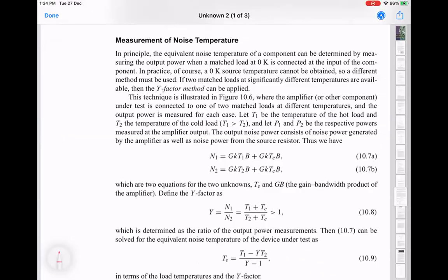So this is a model for an amplifier just from the input and output. It looks like a resistor for anything that is connected to input, and that resistance should be 50 ohms. And it looks like a voltage source with some resistor in series, and that also has to be 50 ohms. This is the ideal case.